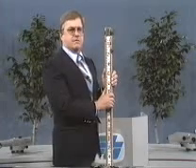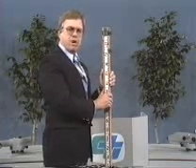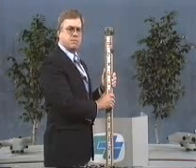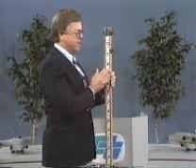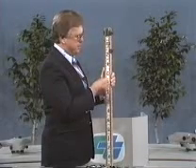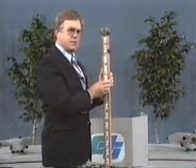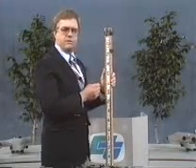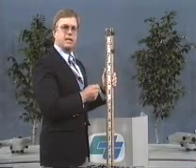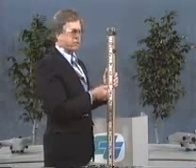Now what this does is facilitate setting an elevation in the rod. When the instrument sets up and reads the elevation on this rod set on the benchmark, the instrument man can tell the rod person what the elevation is. Let's say, for example, that the rod reading is 109 feet and then 1/10.